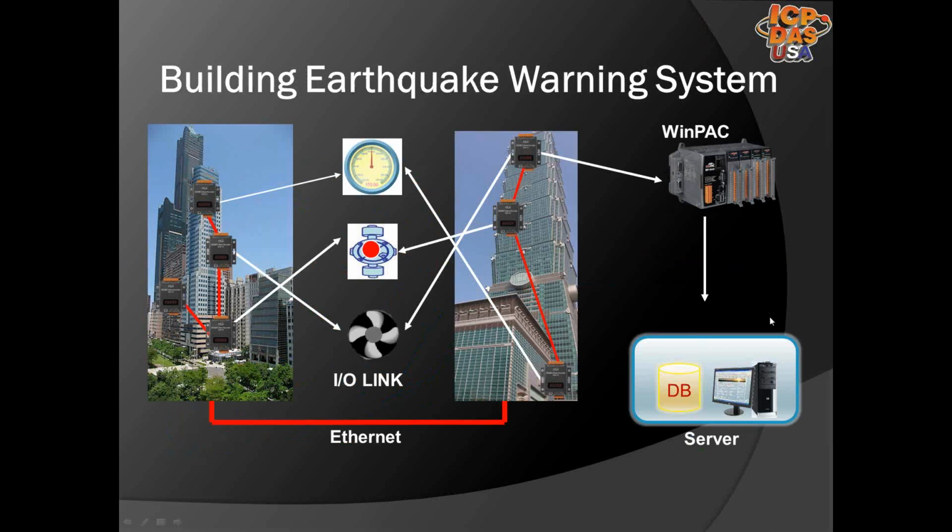Seismic recorders are also being used in building earthquake warning systems. They are installed on different floors of a building to monitor seismic activity. They are networked together over Ethernet cabling. In case of earthquake, a series of automated events will be triggered, including lights for visual alerts, the shutting off of gas and water main valves to prevent fire and water damage, preventing accidents in operating rooms, and the shutting down of industrial processes.